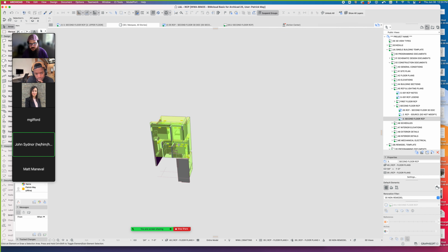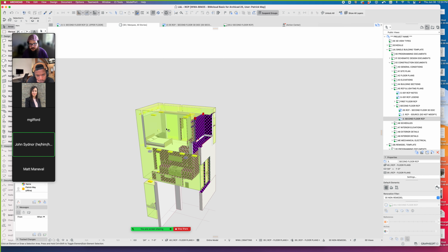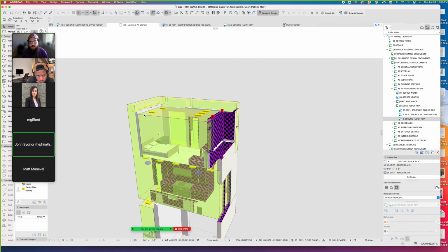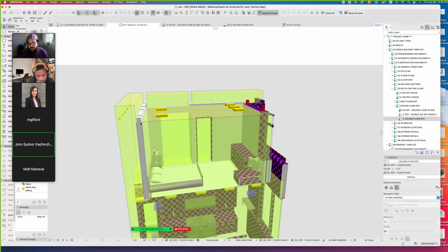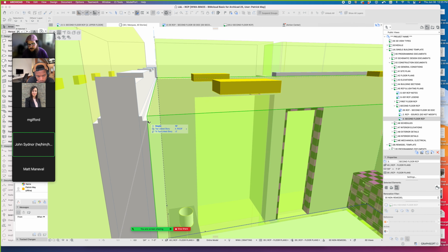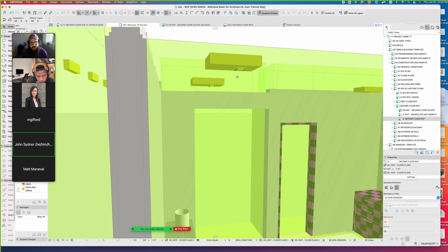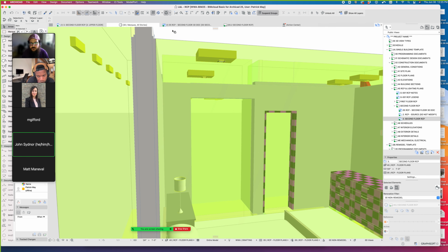If I'm looking right here, it looks like when I copied and pasted, that was a little bit screwy. Anyway, this room right here, that zone, is definitely not at the ceiling height. So this is the sort of thing that if you're going to use these automated annotation features, you're going to have to make sure that you're modeling to that level of detail so that the zones are actually set to the height of the ceiling, which looks like it's actually right there if we turn that layer on. In fact, we can verify that it's right there because that's where that can fixture is at, and that would be punching through.